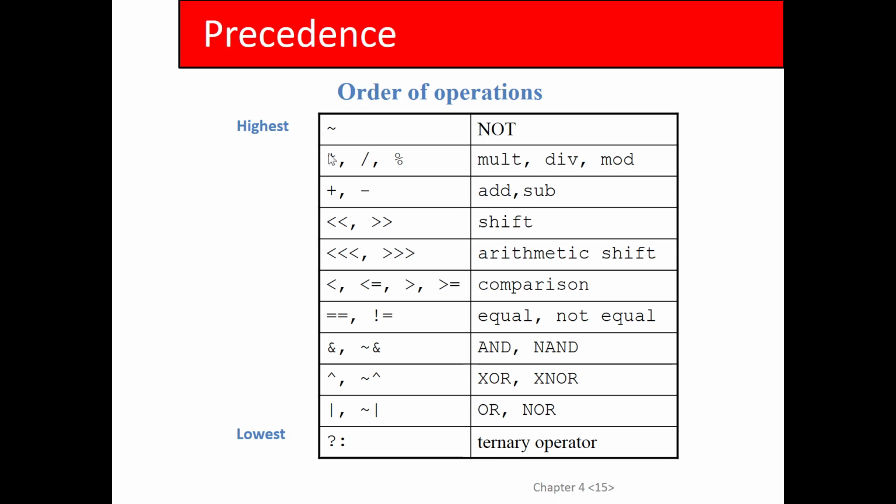You guys with me? Now, how does that apply to a left shift, though? That doesn't make any sense. If you're shifting to the left, you wouldn't be shifting any sign bit into the right-hand side. That doesn't track. But it turns out that the reason why you need an arithmetic left shift is that if your shift amount is negative, then it becomes a right shift, right? So that's why they have both.